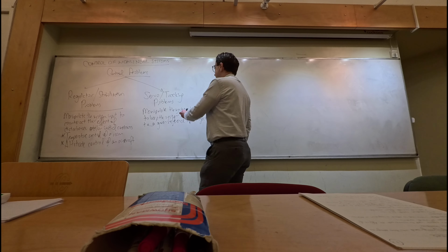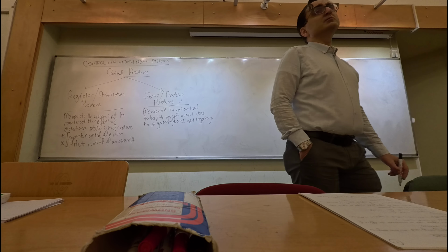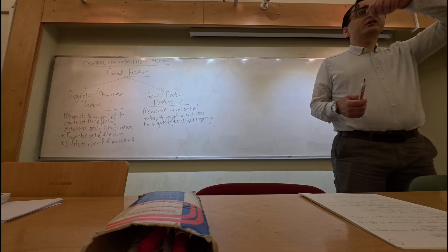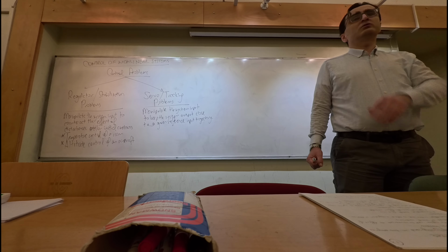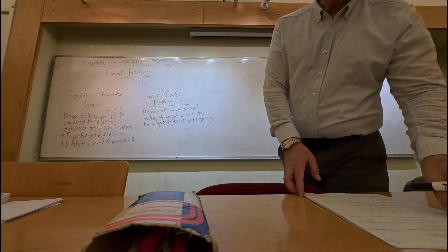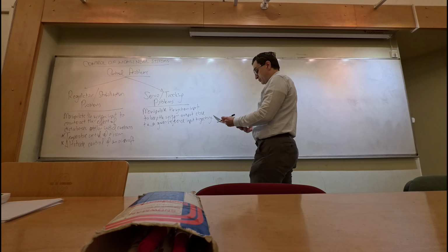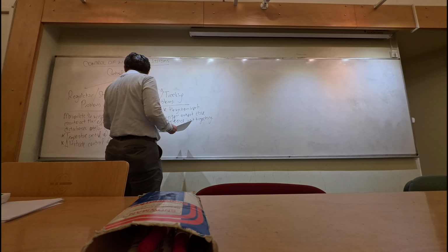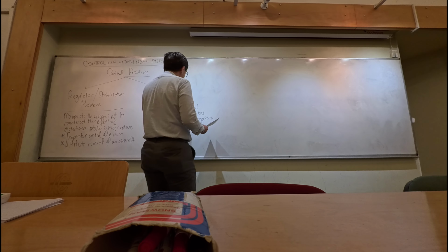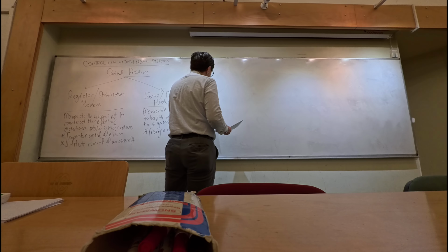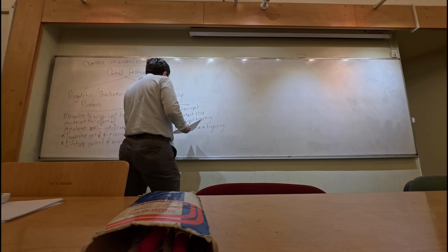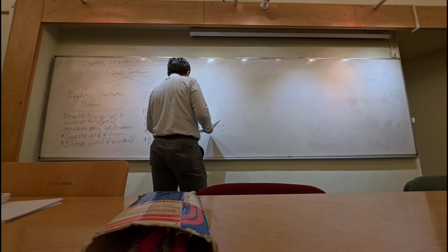And in servo problems, things change a little bit. In this case, disturbances are less important, and the reference input changes are more important, actually. The reference might change in a fast way, and we would like the output to follow the reference input as closely as possible. So the emphasis is on the reference input. So we are trying to keep the output close to the reference input. Examples are making a robot arm follow a trajectory, or making an aircraft fly along a specified path.